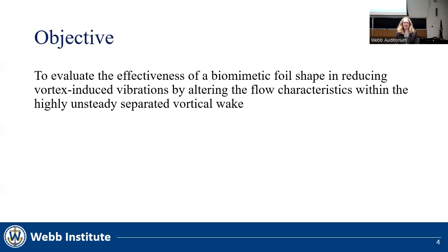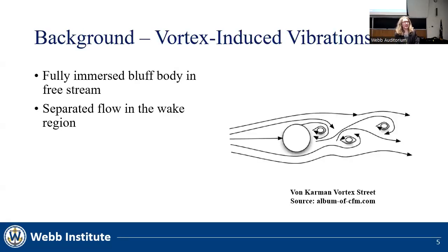The objective of this thesis is to evaluate the effectiveness of a biomimetic foil shape in reducing vortex-induced vibrations by altering the flow characteristics within the highly unsteady separated vortical wake. So what are vortex-induced vibrations? Vortex-induced vibrations are vibrations that are caused by oscillations in the wake region of a bluff body.